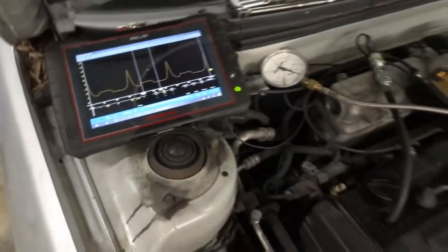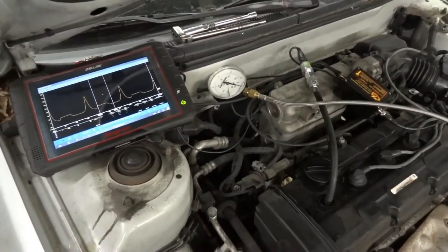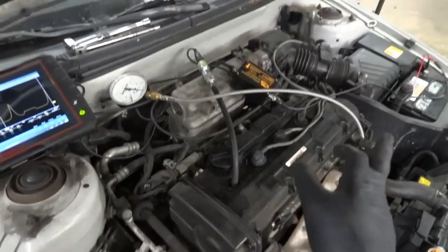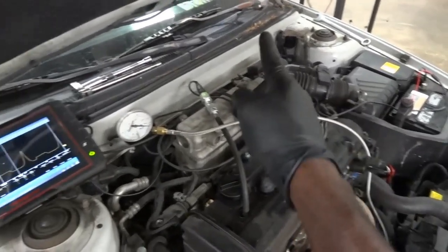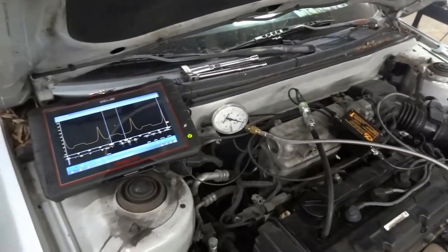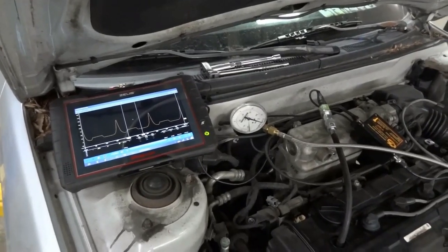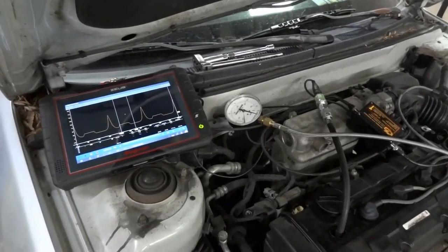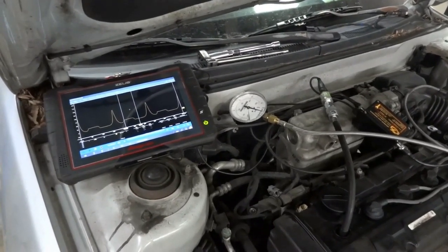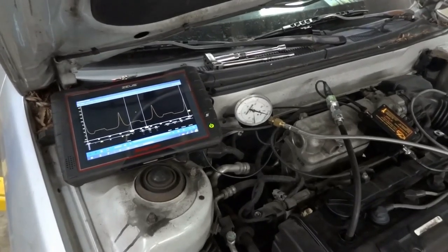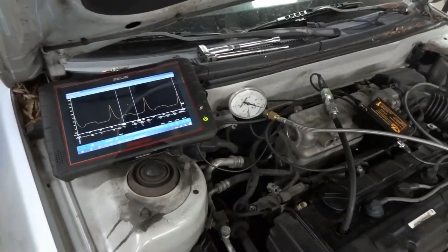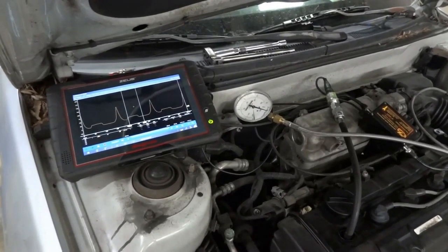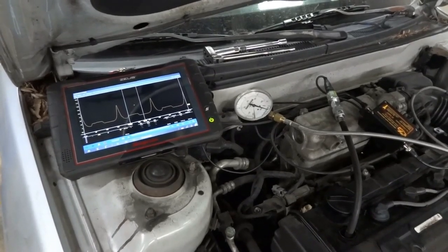So right now what I'm gonna do is get the tools out of here. I will tighten everything back up. I'm gonna reinstall the O2 sensor. Where is the O2 sensor? It's somewhere over there. I'm gonna reinstall the O2 sensor, and then we're gonna connect a scan tool to the vehicle to look at the data. I'm gonna look at our fuel trim numbers and our mass airflow sensor data PID. Remember, the mass airflow sensor data PID was low at higher RPMs. So right now, with the exhaust system replaced, our exhaust system is no longer restricted. Our mass airflow sensor data PID should be higher at a higher RPM, okay?